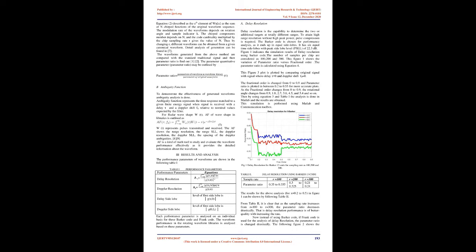2. Generation of waveforms. FRFT and equations. The idea of FRFT was suggested by Namias. This concept is used to compute the FRFT in the plane specified by time and frequency. This is called an axis rotation angle. The ordinary Fourier transform is raised to a fractional power. For the generation of a waveform library using FRFT, the number of chips, called N, is used in a code sequence. One of the necessary components for the calculation is the number of samples per chip, R, of a sequence. Thus by using R, the total length of a digital signal can be calculated as n equals N times R.